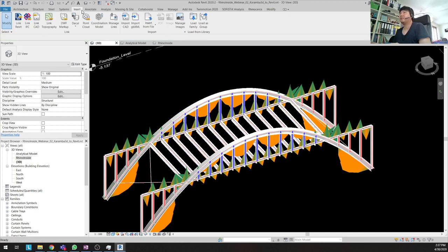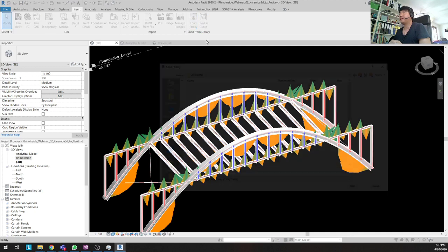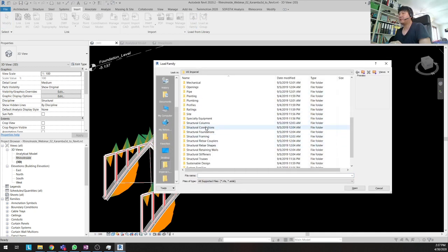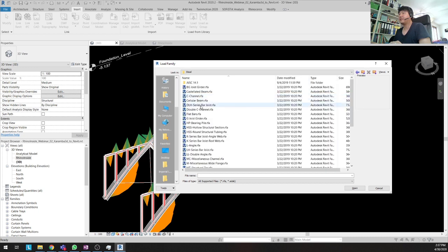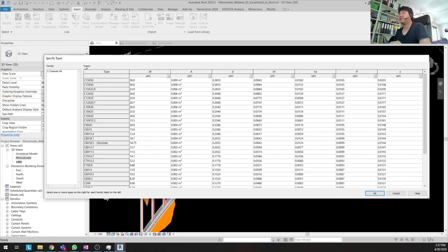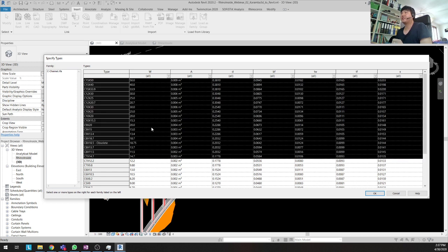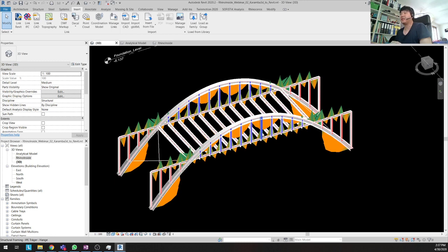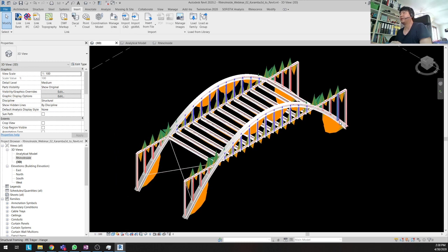So what it means, you might know when you use Revit, you can load family, and then there we can load, for instance, structural framing and steel member. When we load this member, this table chart automatically pops up. This is called a type catalog file, and of course we can script additionally to generate all these different members from Karamba3D to load all the different types of members in Revit. Then that also makes your workflow a bit easier in a practical way.